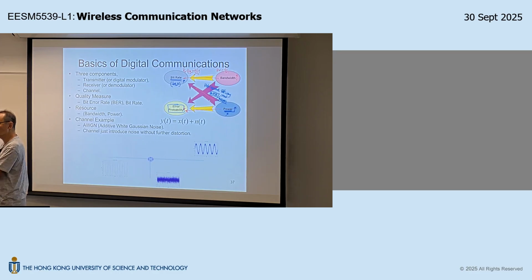So with 2 gigahertz carrier frequency, you may have very limited bandwidth available. So you want to use this family to save the bandwidth, because bandwidth is much more expensive at low carrier frequency, right? You want to save this at the expense of extra power. So that would be the modulation family you choose for scenario B. Is that okay? So this is a toy example to reinforce my statement.